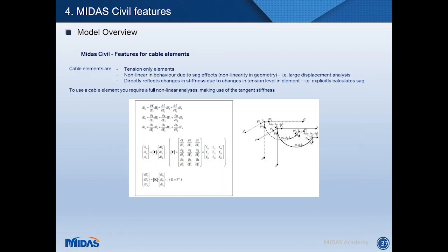Moving on to the cables. Cables, by definition, are non-linear elements. So they are tension-only elements. They do not take any bending, and they show a high non-linear behavior. So based on the level of stress in the element, its stiffness will change. If you want to use a full cable element, you need to use a fully non-linear analysis, making use of the tangent stiffness of the element.